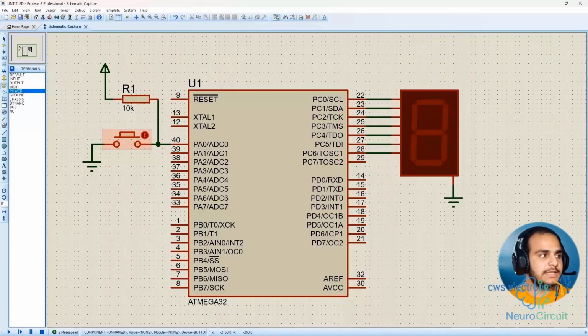In this way, even when our button is released, with the help of this resistor, we are completely controlling the environmental noise. Now, the microcontroller actually has this same resistor built in. That is, as I said, many of these features are already built into the microcontroller itself. This is one of its most important features. For example, in your project, you might want to use several buttons, and in your circuit, you would have had to use a lot of resistors, but the microcontroller has provided this for us internally.